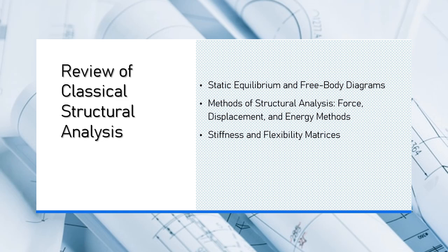2.5. Limitations of static equilibrium. While static equilibrium provides the foundation for classical analysis methods, there are some limitations. Static assumption: static equilibrium assumes that structures are not subject to dynamic forces, such as earthquakes, wind gusts, or traffic. For such cases, dynamic analysis is required, which accounts for time-dependent effects.